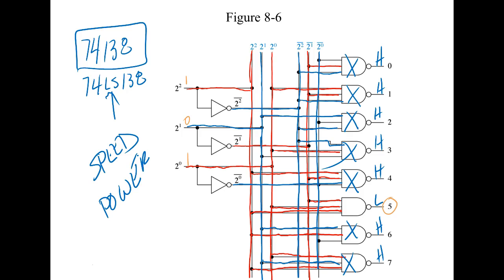So the same thing's true in digital. The faster these things run, the more power they consume, which means my power supply has got to provide more power, right? Does that make sense? So those center letters are telling us the speed and power characteristics. That means once you looked up one LS chip, you pretty much got all of them, because they're within that family. You understand? So you would know basically the fan out. What's the fan out, by the way?